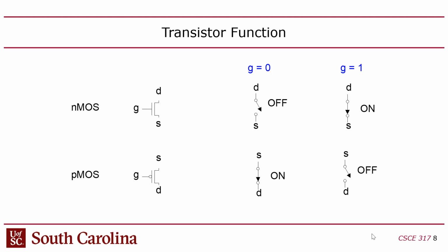The only thing about MOSFETs is that they don't have an arrow to show which way the current's supposed to go. But it actually doesn't matter because these are symmetric devices. You can send current from drain to source or source to drain. In fact, there's really no difference between the drain and the source; they are conventional. Normally, current goes from the drain to the source.